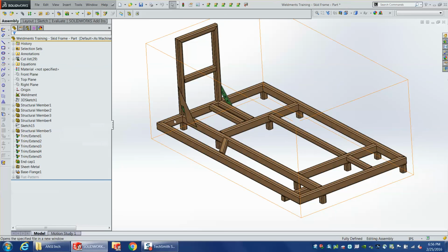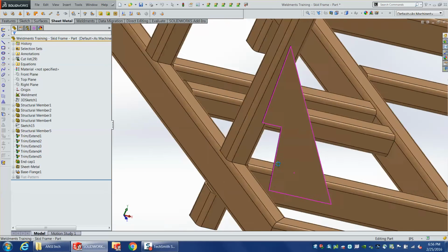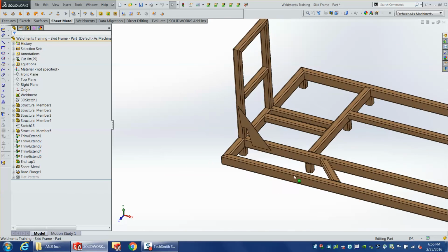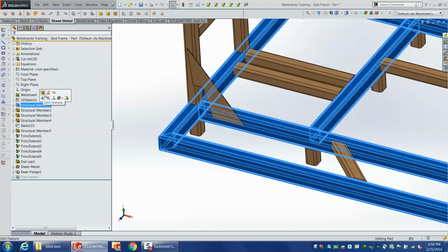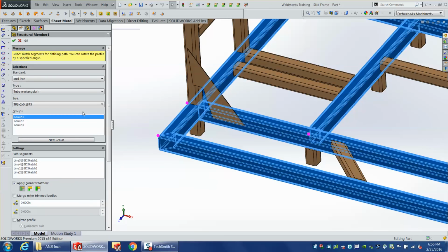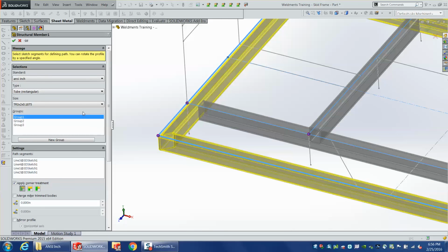So the profile is embedded in the feature once you use it. The problem is, if I had a bunch of them, all my special tubing profiles, and I want to send it to somebody, they won't be able to change it to a different one of my custom profiles, or even reuse that profile. As long as they don't edit it, it's there.